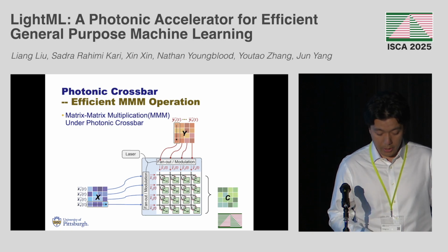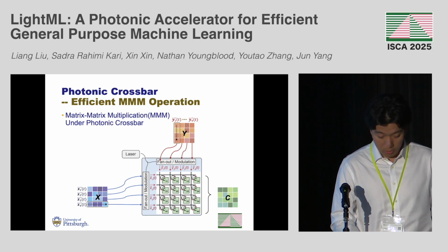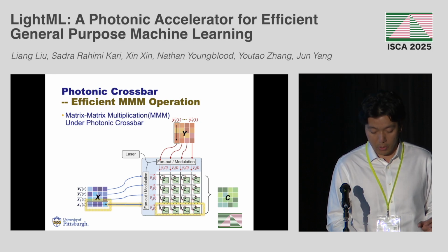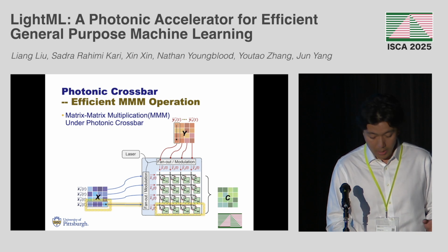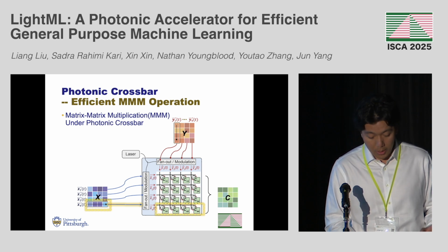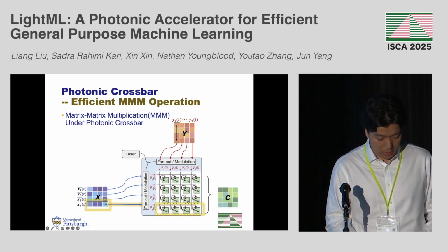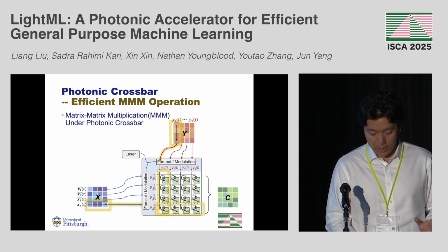We show an example of a 4x4 crossbar device, which has two directions of input. In the horizontal direction, we derive matrix x from 4 horizontal vectors, and each of them is sent to a row modulator and converted to a light signal. The light signal will propagate to all units in this row. Similarly, in the vertical direction, the vertical vector is sent to the corresponding column of the crossbar.